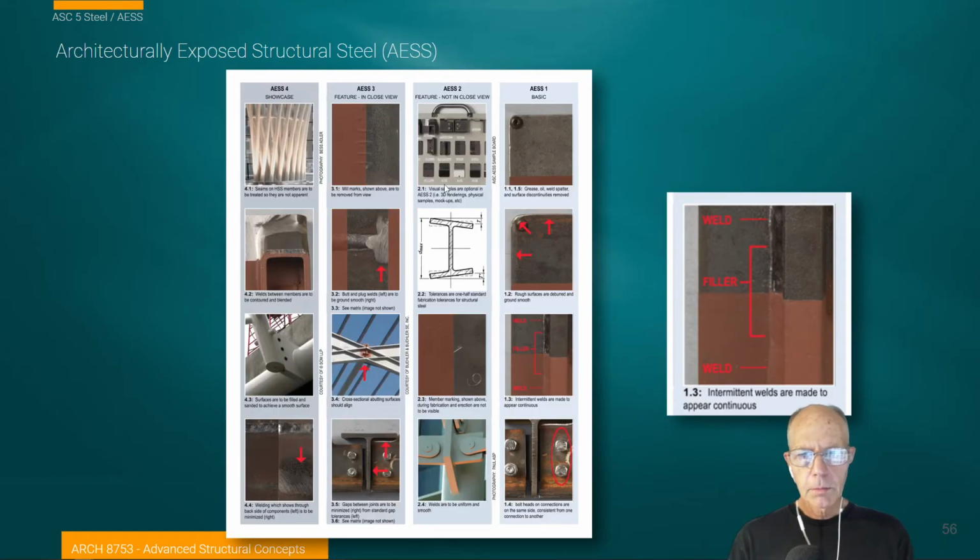So here is a chart. It's not that we're going to memorize a chart, but the idea is that it shows you the ideas about how things need to look. Here we have that highest level, 4, where we have once again that column system I showed you at the entry condition with that strong side lighting. And so the quality of the finish needs to be very high.